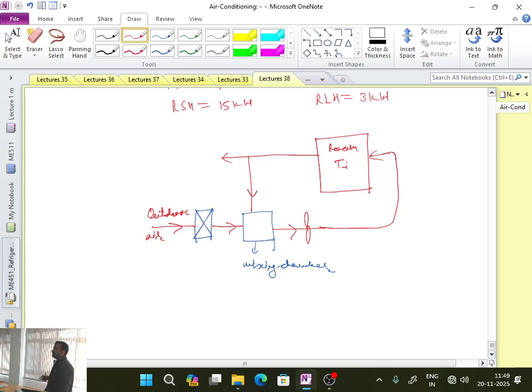It means that first we are just cooling the outdoor air only. We are not mixing O and I. We are cooling the outdoor air, bringing that to some state 2, then state 2 and intermediate state I are mixed together to bring some supply state. Is this point clear? The diagram on the psychrometric chart will be represented with a different arrangement.